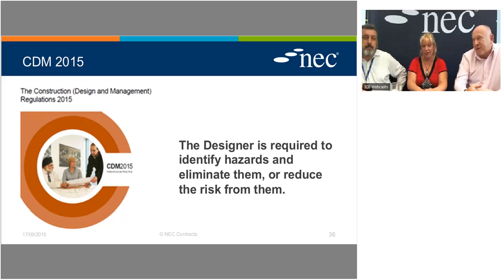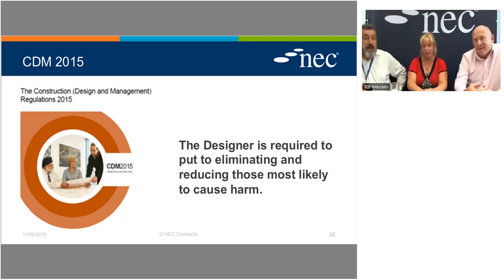Yes. Okay. Interesting. Most effort has to go to the most risky activities where most harm is likely to happen. In construction, that tends to be things falling, people getting squashed by machinery. So you need to concentrate on that. In my own line on highways, you've got to think very carefully about where the traffic is, how close to the work, and what you're going to do to try and keep the two separate. Most effort where the harm will come.